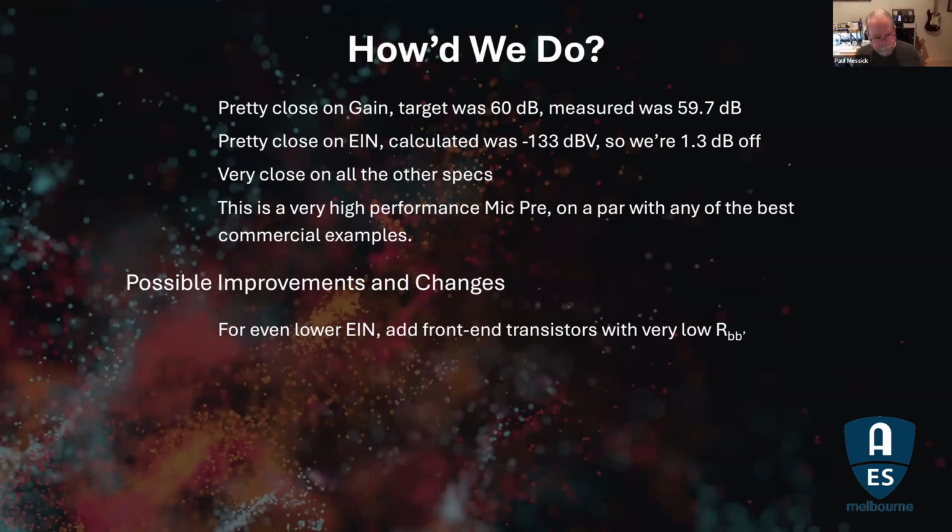So it's not a panacea. If cost is an issue, when this thing is not cheap, there are some other op amps you could use. You could use a 1656, which is about a quarter the cost of a 1612, or 5532. And there are lots of mic pre's that were made with those. It's not a great mic pre, but it's an inexpensive one. And you'll see that sort of thing at the input to a lot of prosumer sort of gear.